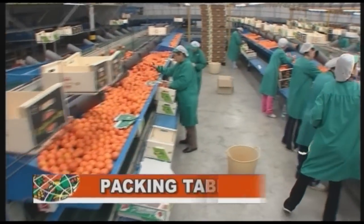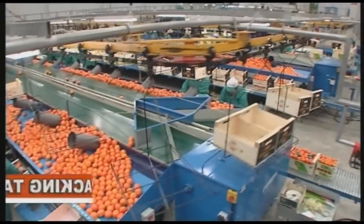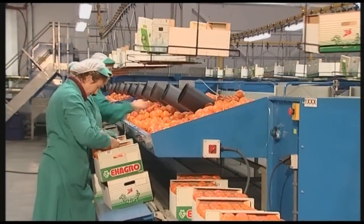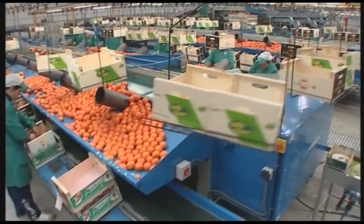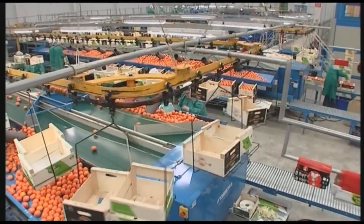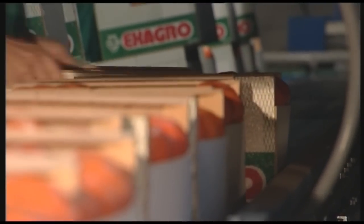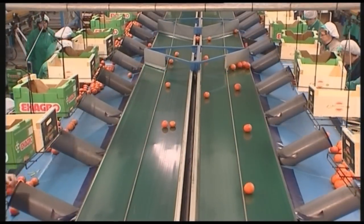The frontal packing tables are used to fill the boxes manually with the fruit coming from the sizer. Each side of the table can admit 1, 2, or 3 different sizes. The packing table is equipped with 2 feeding conveyors, automatic distribution carts, and packing trays. It also incorporates 2 lower conveyors to evacuate full boxes.